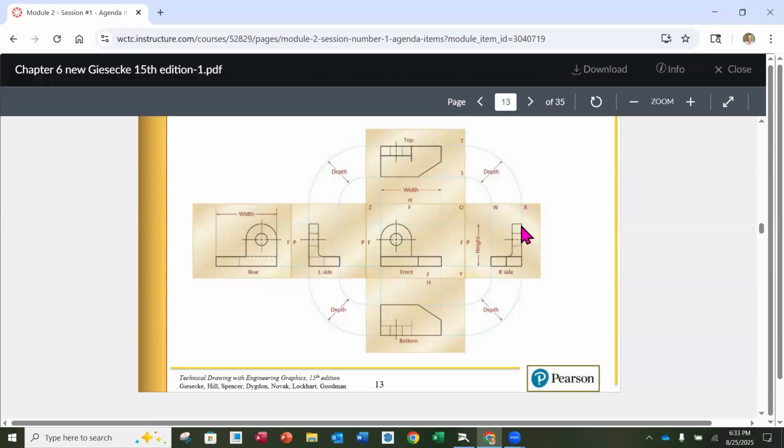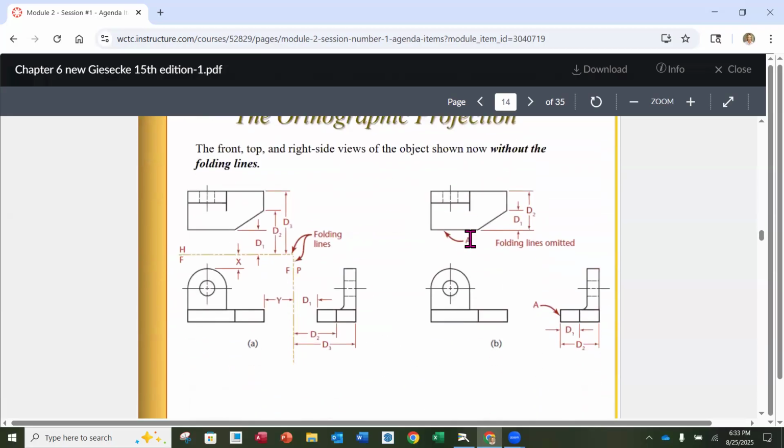If I go over to the right side, notice that that's the very top of the backwards L, if you would, in the right side view, okay? The bottom of the part, in line across that right side, okay? If I go to the left side, same thing. And then remember, this is an extra hinge. This is the back side brought forward on my box. So then these are all in line across the top, the bottom, and the centers of those holes, too, every one of those elements, okay? All right, this is good.